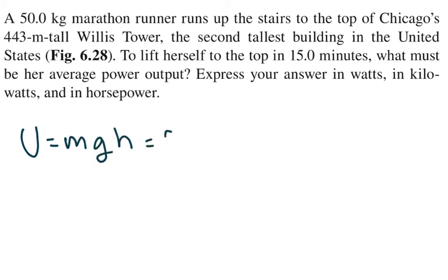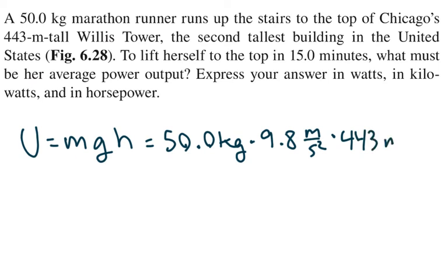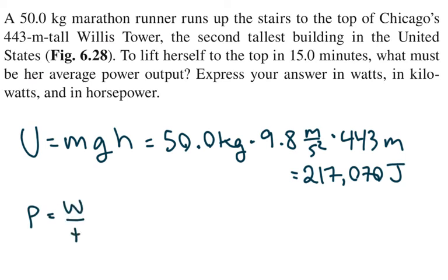So here that's equal to 50 kilograms times 9.8 meters per second squared times 443 meters. This gets us a value of 217,070 joules. But we're not done yet. So we have to take this and use power equals work over time.